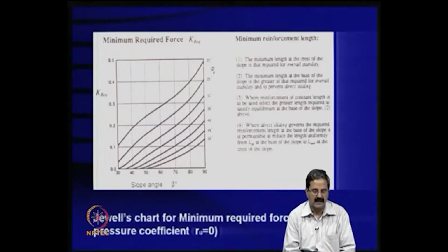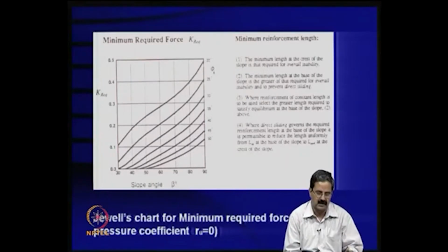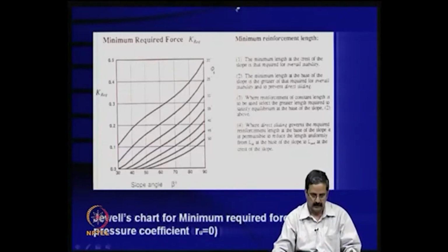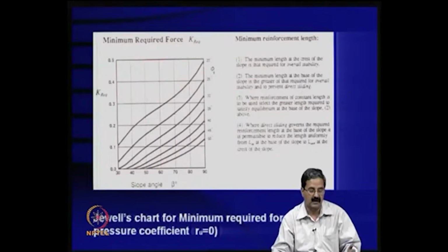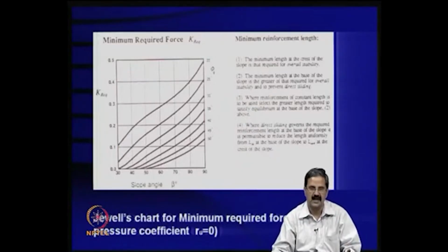And if there is an earthquake that comes, one can even calculate the dynamic earth pressure increment also. So this concept is very important in terms of understanding what is the resistance required to see that it can sustain some horizontal force, either in the form of lateral pressure from its own weight, or because of the earthquake, or because of the seepage forces and all that.